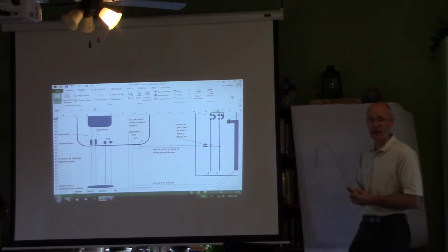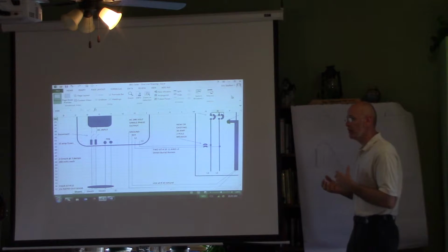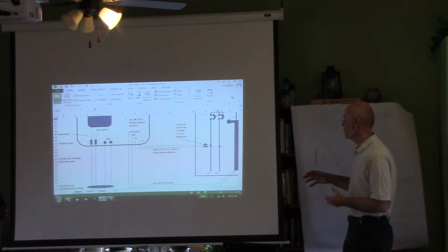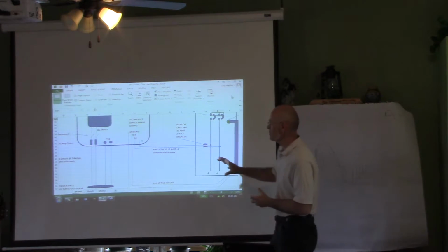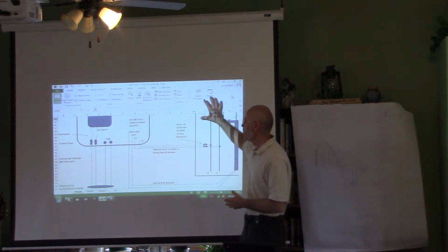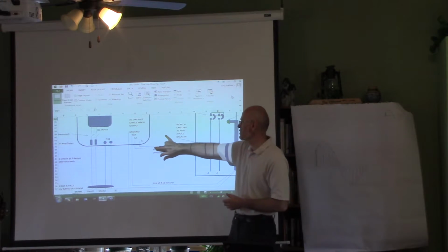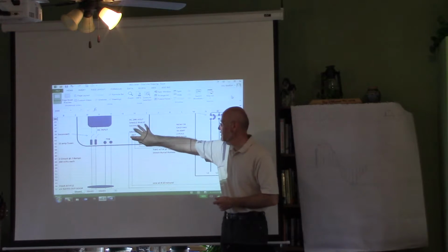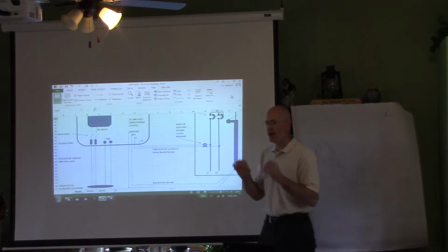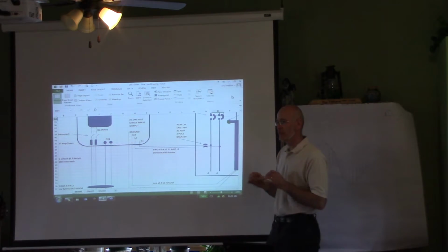So when does it come back on? Well, here's where we come to that interconnection standard, where we've been able to force the utilities to accept this power by creating a worldwide international standard that says, hey, this device, the inverter, is going to wait for 5 minutes after it sees new power.